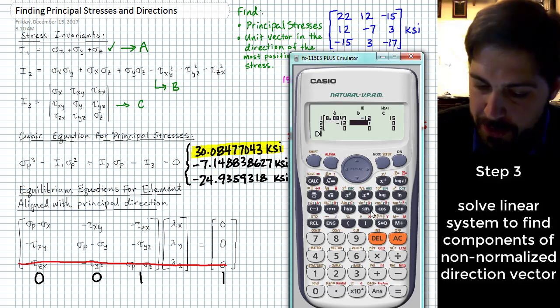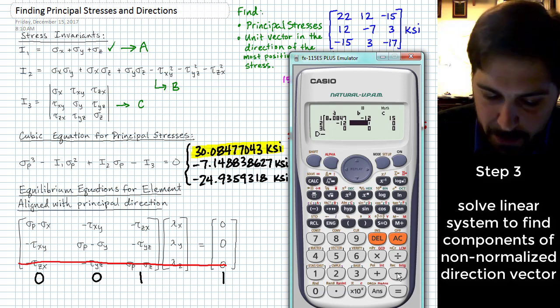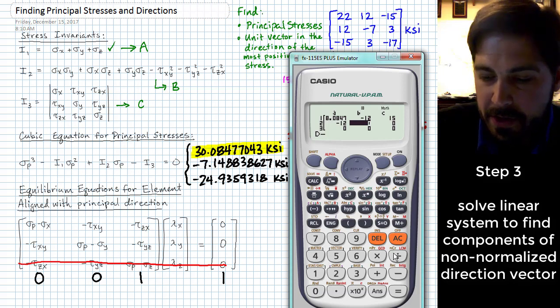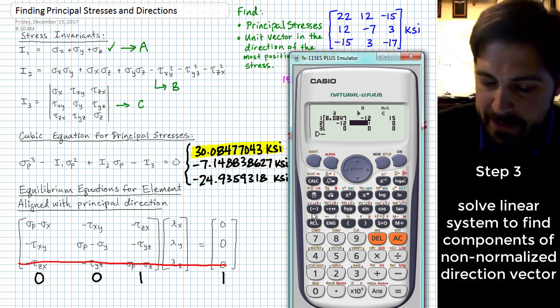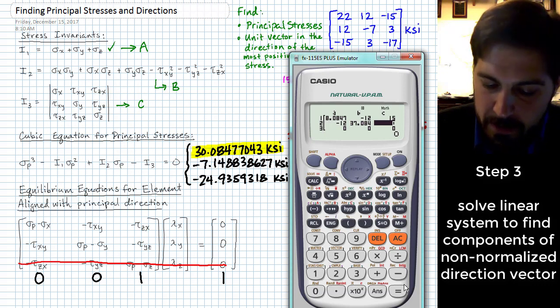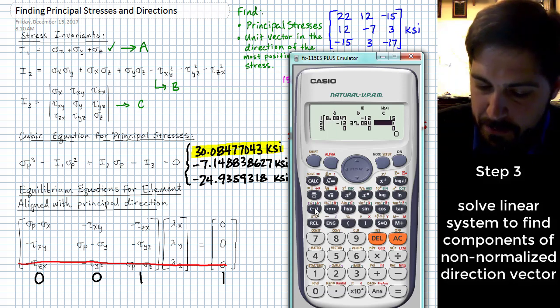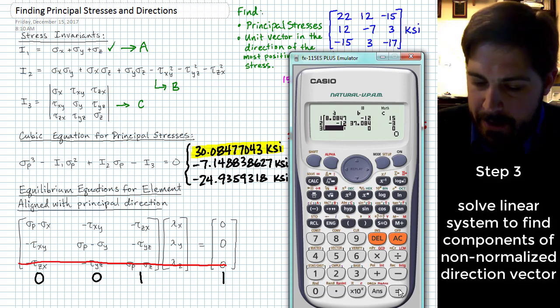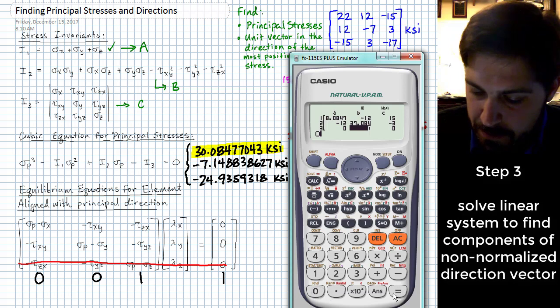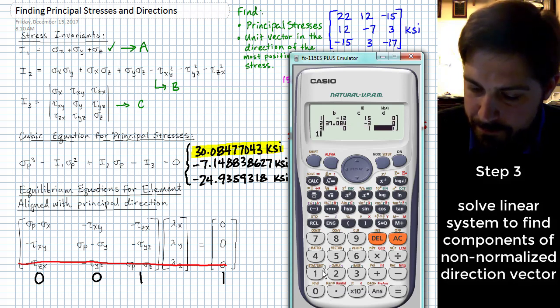We will then have what was stored in D minus, and then we have to look and see what the normal stress was in the y direction. It started out as negative 7 ksi, so we'll subtract a negative 7 from that. And then the next one there would be a negative tau sub yz. Tau sub yz was 3, so we put in negative 3. And that last row is 0. And then in this next row here, we just put in 0, 0, 1, 1.